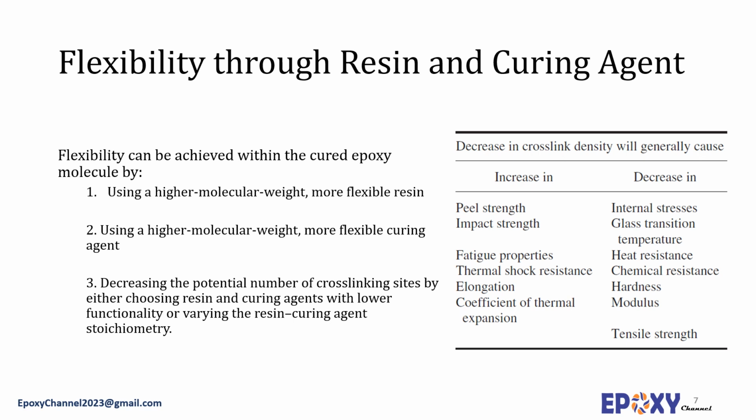There are many other examples of incorporating flexibility into epoxy adhesives by appropriate selection of the curing agent. For example, by changing from hexahydrophthalic anhydride to hexamethylene diamine, one can double the impact resistance of the resin system and slightly increase the tensile elongation at break.